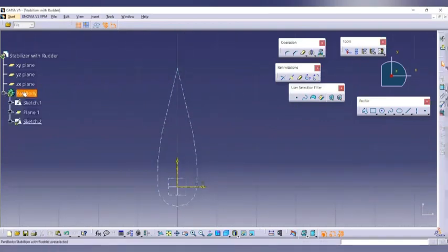This part is quite tedious, so you have to follow one by one. So first off, you click on the sketch that we've made before, sketch 1. It will outline in the color orange. When that's done, you will click on this icon, which is Project 3D Elements, and when you click on it, you have to straight away click on another icon that is Scale.